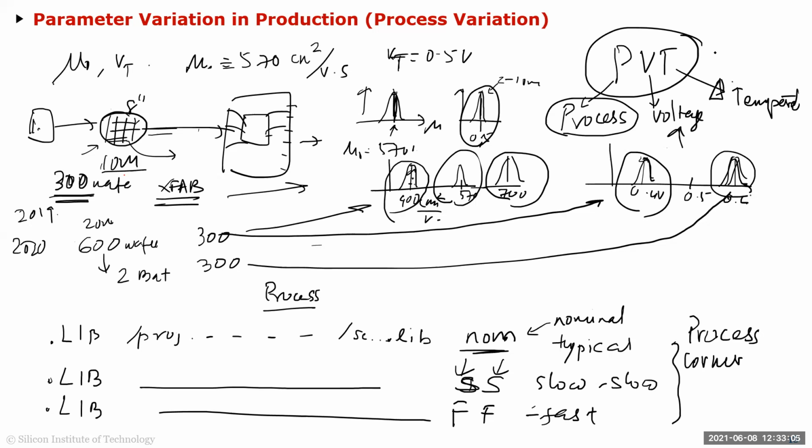Because all IC, like your phone or anything like that, like consumer items, for example, they have to work between -40 to 85 degrees centigrade. But that is ambient temperature, but your junction temperature could be as high as 125 degrees centigrade. Industrial ambient actually has to work from -40 to 125. Automotive and industrial, they have to work with very high ambient temperature as well. Okay, so I'll talk a little bit about the temperature variation afterward. So is everyone clear about the temperature variation now, or any questions?